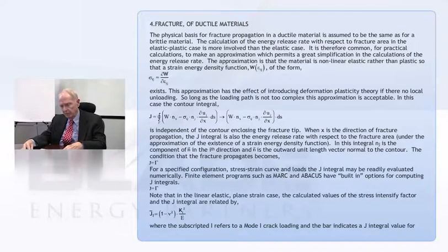They went back and said, well, what the heck? Let's assume that at the crack tip we have a case of loading that can be represented with a make-believe elasticity. Really, in order to have that, your stresses should all be increasing proportionally, and you must never unload. A few things like that. But if you look at the tip of a crack, it's plausible, I would say, that you could get away with that. Furthermore, a fellow named Bernard Budiansky had shown that there are many cases where you can get away with that kind of approximation.